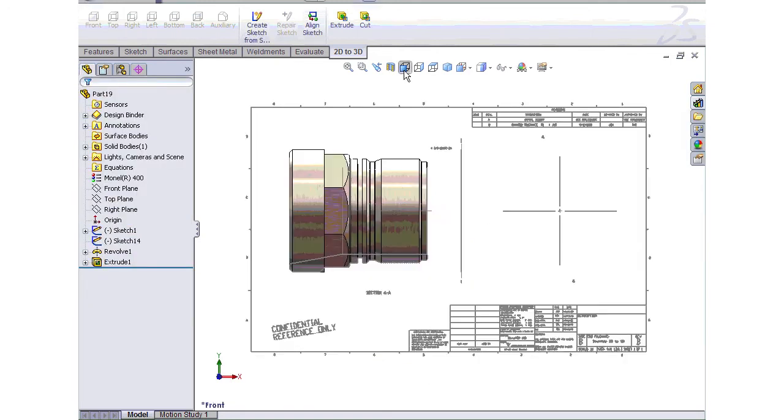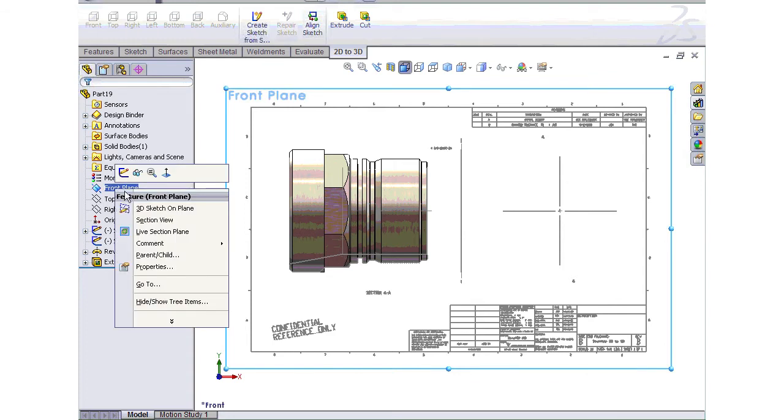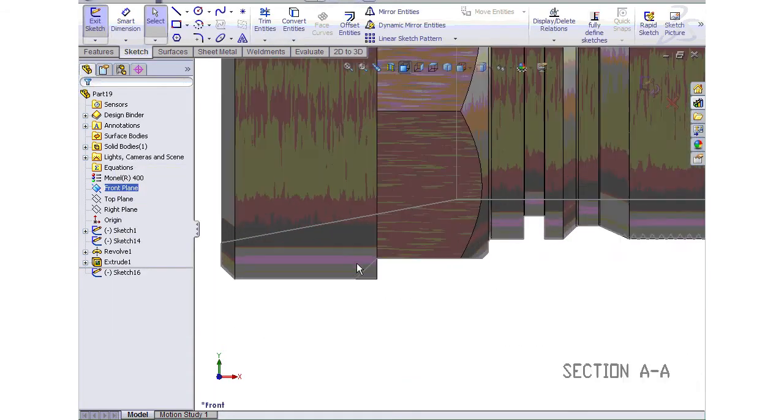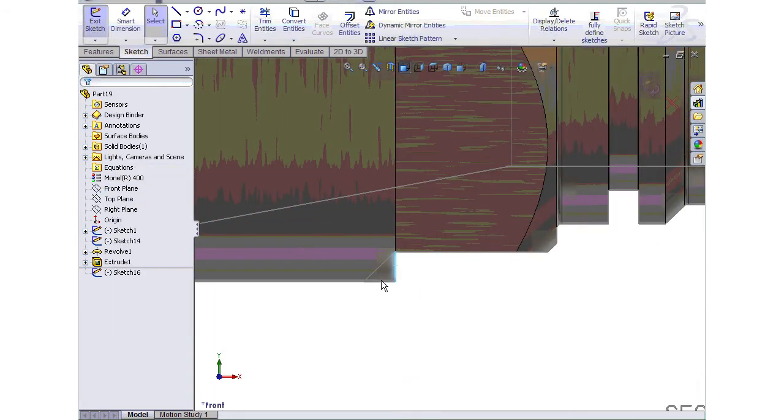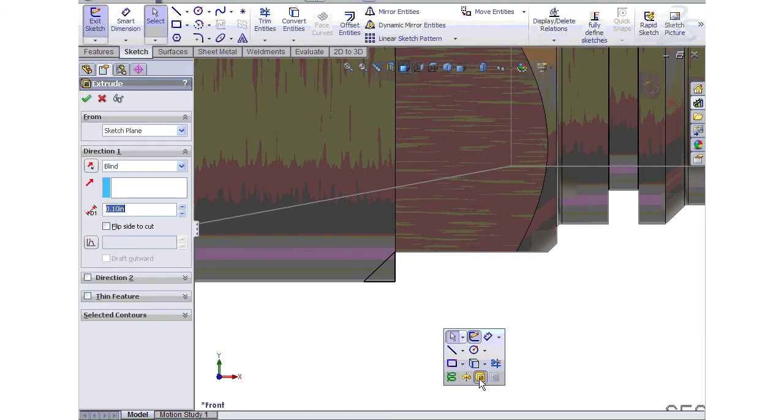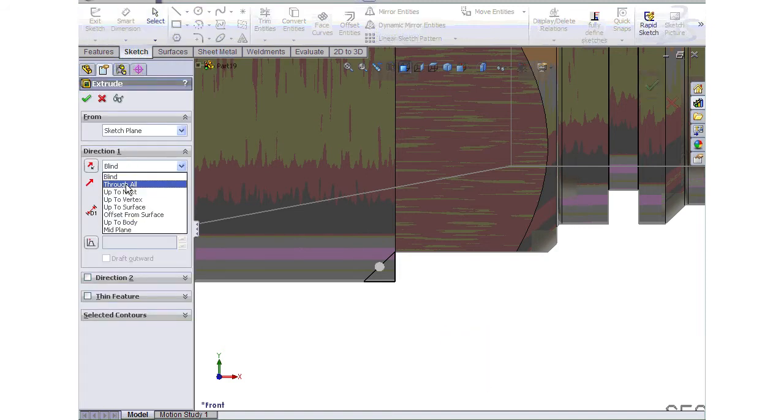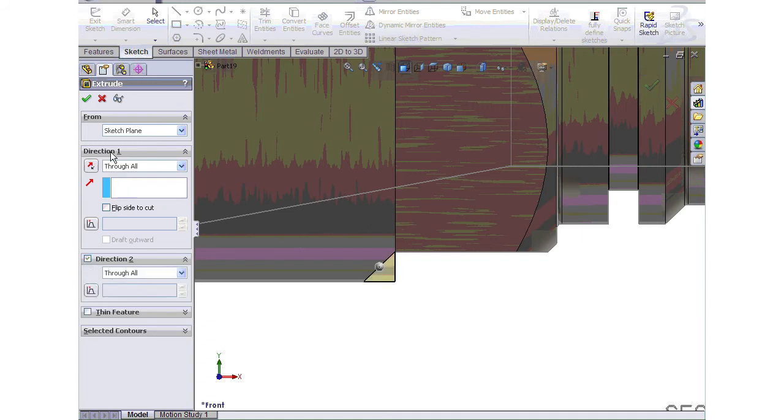According to the imported DWG geometry, the milled flats need to terminate on a 45-degree chamfer. This chamfer can be defined by selecting existing sketch geometry and edges in our front view. Once the geometry is selected, it is trimmed to create a closed boundary. This boundary is then utilized to create an extruded cut feature, which becomes our milled chamfer.